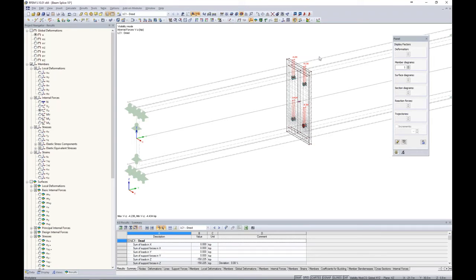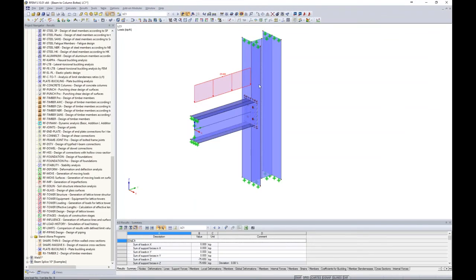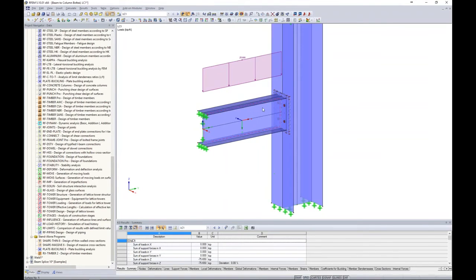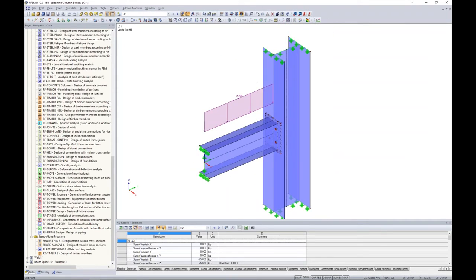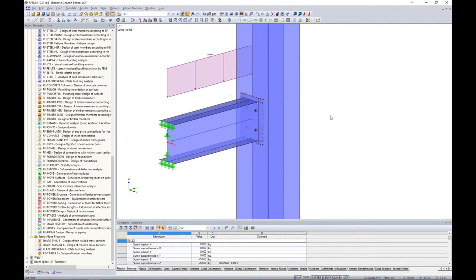Now, this was a completely symmetric design, which was very nice, but we all know that this typically is not the case. So what do we do when we don't have complete symmetry when we're looking at something like a contact solid? For this, I want to jump into my saved model here, and it's just a typical beam framing into a column. Now, I went about it the same way of converting 1D member elements from my beam and my column. I even went about it the same way for my contact solid for my plate element, but there's something that's slightly different here.